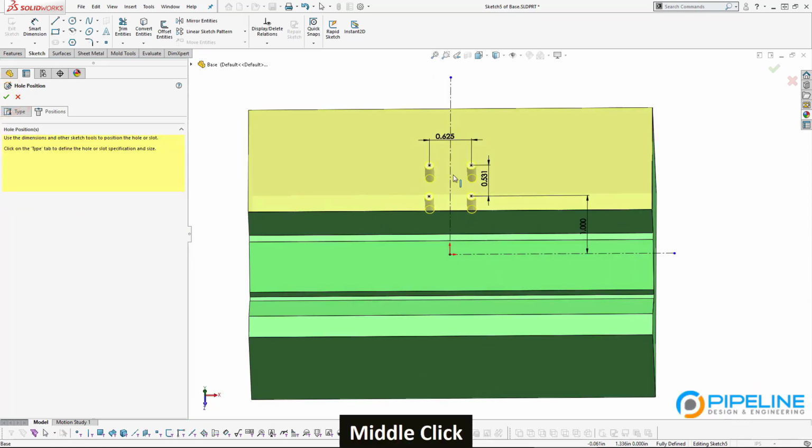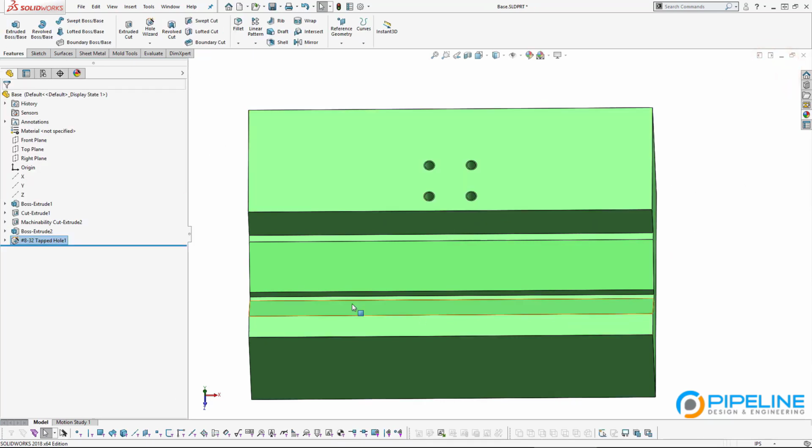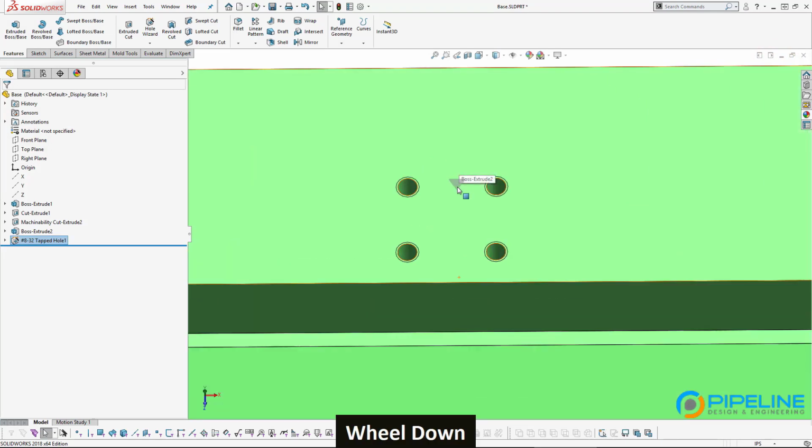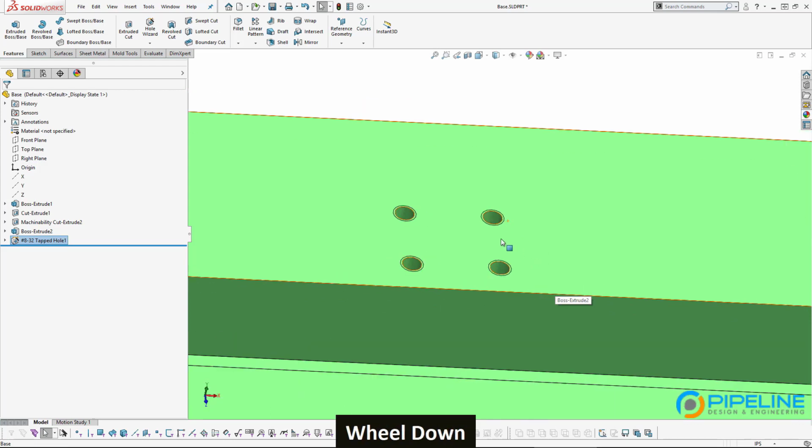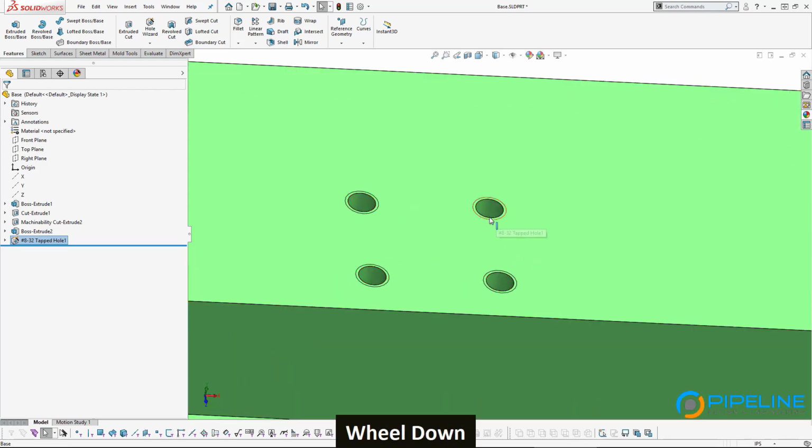There you go. So now we know if we drill these holes, we'll be able to align the toggle clamp with it. I'll go ahead and hit accept. You can see these little lines around the hole are an indication that the hole is tapped. SolidWorks won't go through and show the little helical shape that a tapped hole would have that a screw would engage with, because that takes processing power, and it's not really necessary to show those details.